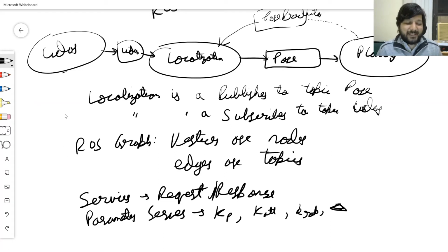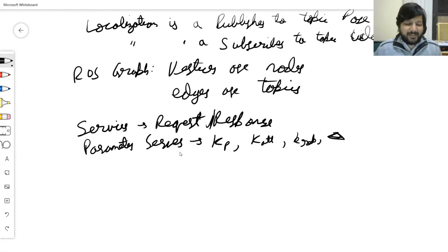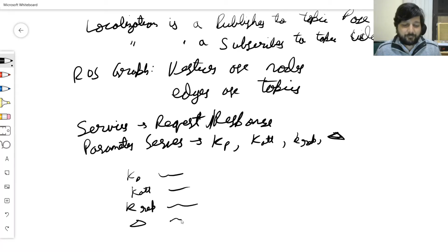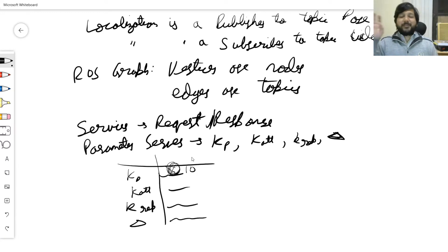What the parameter server does is it's a server that keeps a list of all parameters and their current values. By calling in certain requests, you can update its values or you can get its current value. So in your programming scripts, for all constants, you just access the parameter server to get the current values, and these values can be varied without the need to compile and install. And that's how we handle all parameters.